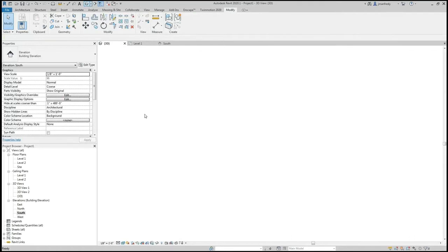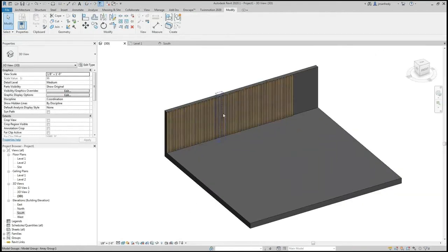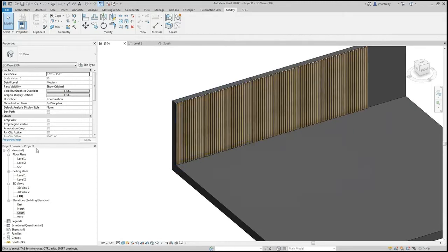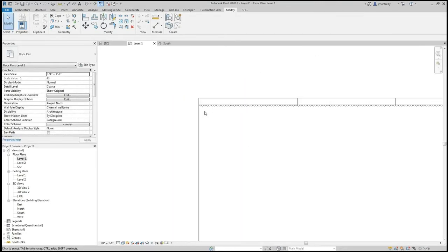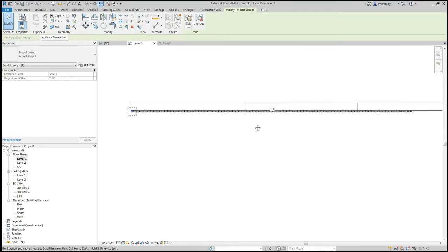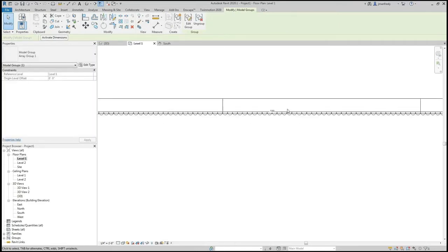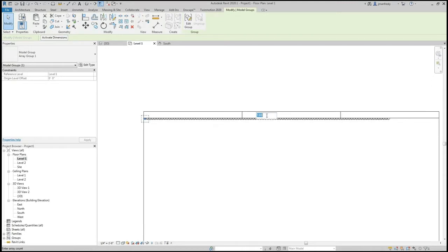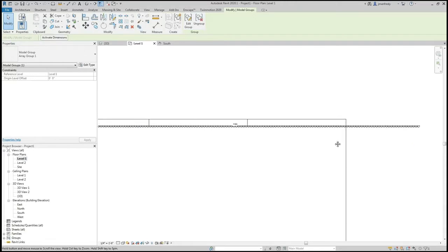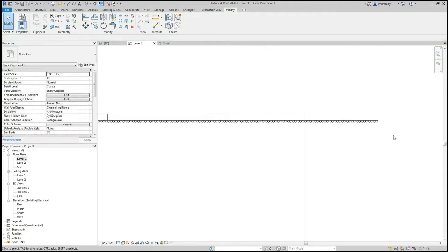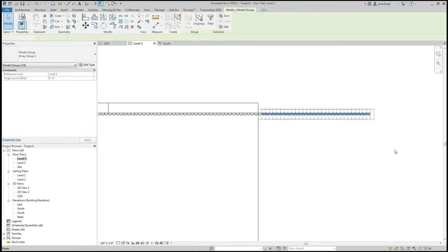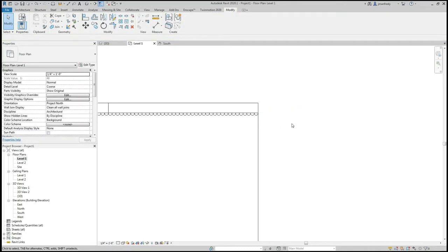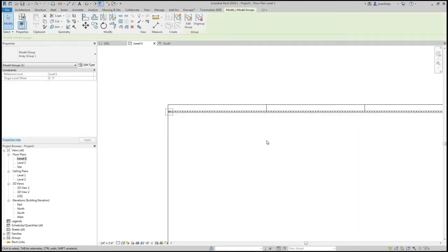And if I go back to my 3D view here, you'll see I've created 100 of these things. Back in plan view, if I simply were to zoom in here and choose one, you'll see that this bar here shows up, this little dimension string with the number 100, which I can then manipulate, make it 150, for example, and I've got another 50 added to the end of the array. For example, there. So I can tweak that number, or obviously I can simply just drag here and just delete what I don't need. If these are in excess copies, I can simply delete those. So clicking on the one,